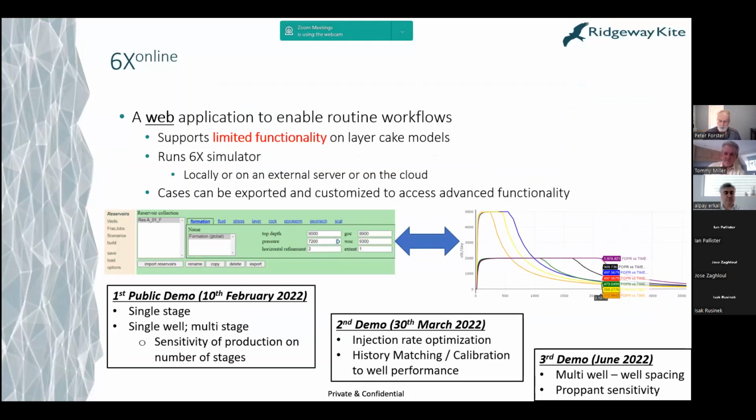So you end up with a flat square model. There are a couple of keywords in the data set that say, this is where the top of the model is, this is the extent of it, this is the thickness. You could take those out and put in an include statement that pointed to a file exported directly from Petrel in Eclipse format, and that would bring in the geometry and the geological properties directly from that model.